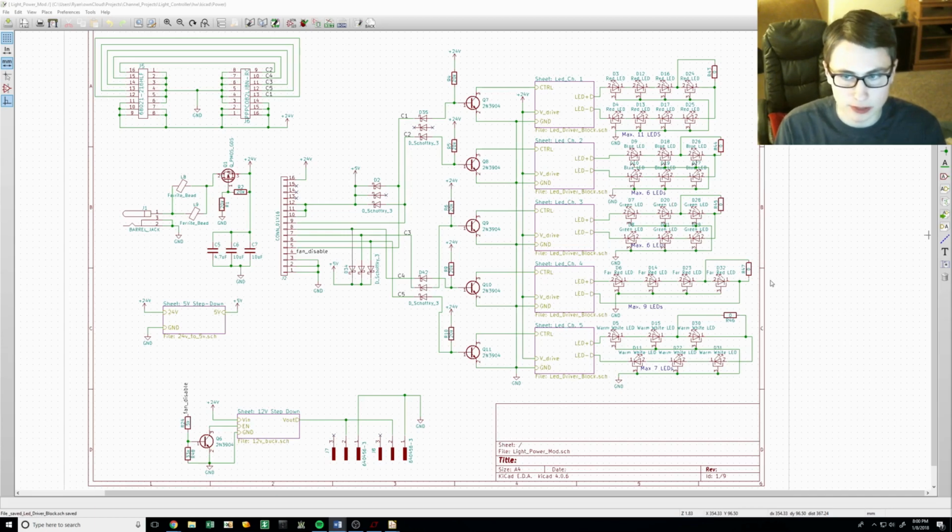Since lumens only measures visible light, infrared light cannot be added to this number directly. The light output intensity of 1,442 lumens was calculated using the minimum rating on the datasheet. I hope to measure the actual performance of the LEDs in a future video. You'll notice that each channel has a 0 ohm resistor across an LED. This is to make accurate current measurements by shorting out one LED. Now let's talk about the LED controllers.